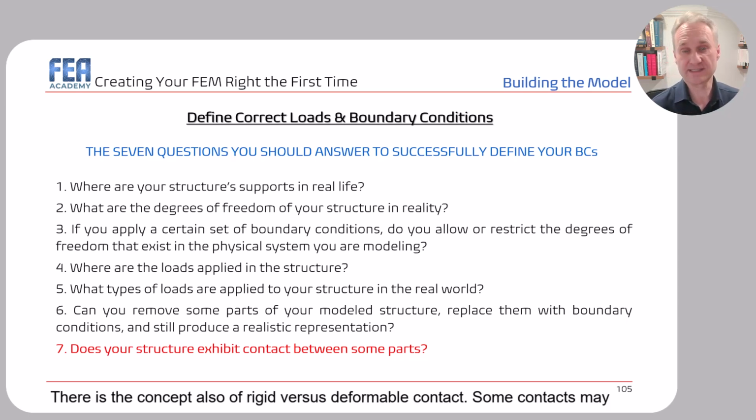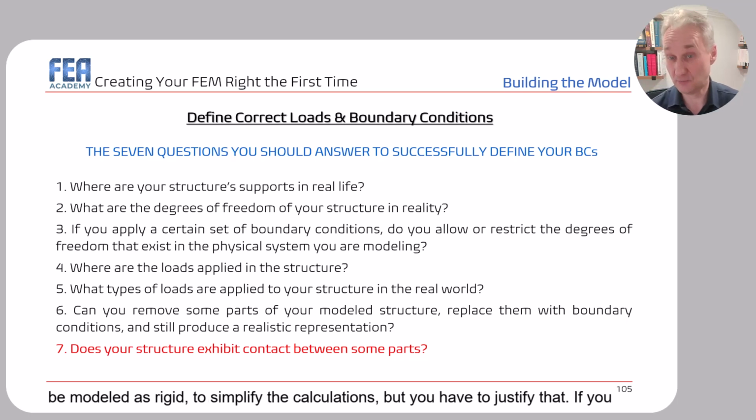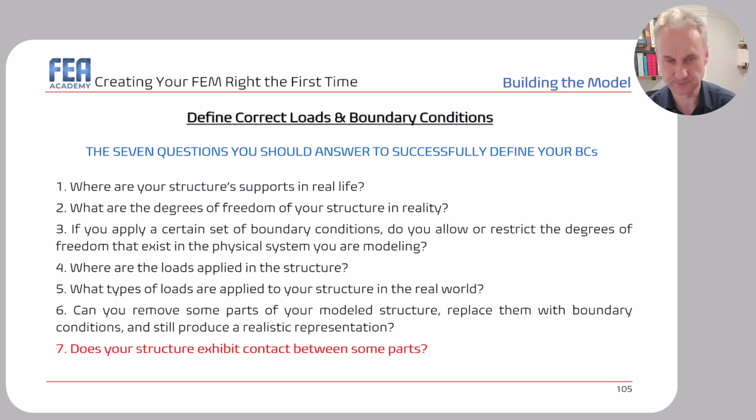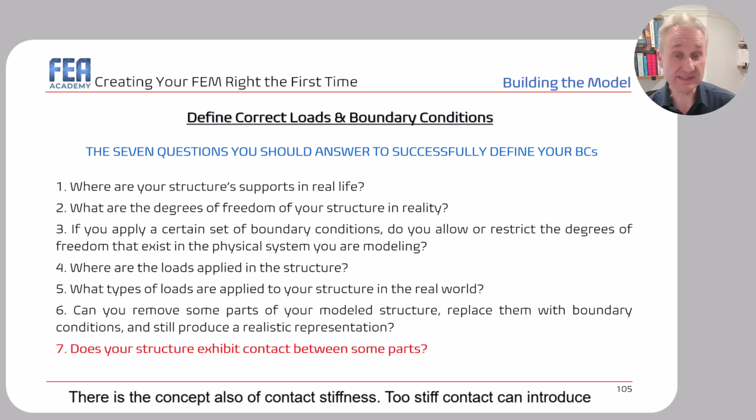There is the concept also of rigid versus deformable contact. Some contacts may be modeled as rigid to simplify the calculations, but you have to justify that. If you are not able, it means that you have to consider a deformable body. There is the concept also of contact stiffness.